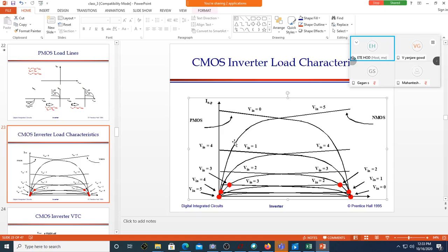Can you see this is the one we are referring to? The NMOS transistor is in which region? Here. Yes, sir. Which region? Cutoff is off, not. Sir, why is the slope not constant here? Which slope? This slope. Here, both of them, lambda is non-zero. Lambda is non-zero. There is channel length modulation. Correct?